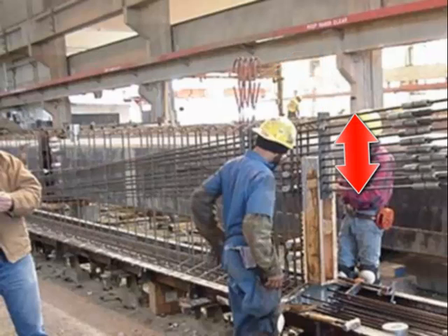The template plate can be adjusted vertically by moving the jacking frame up and down. This means that strand locations at the ends can be adjusted continuously up and down, not just at 2-inch increments, but any increment. However, the relative distance between the strands is typically the same, 2 inches.